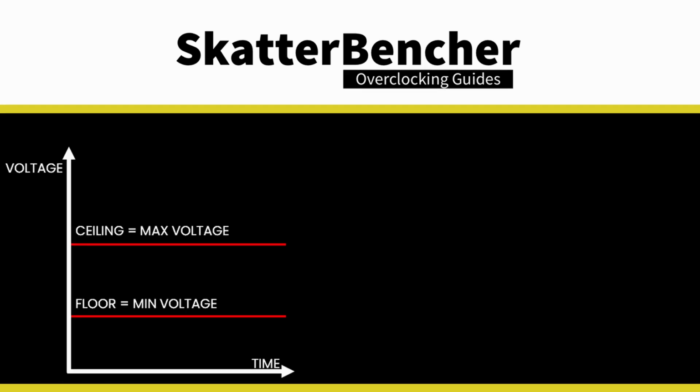We can configure the voltage suspension by setting the voltage ceiling and floor. Obviously, the ceiling is our maximum voltage and the floor is our minimum voltage. We can configure the ceiling and floor in static mode or dynamic mode. In static mode, we set a maximum and minimum voltage. The voltage suspension function will try to keep the voltage between these two levels.